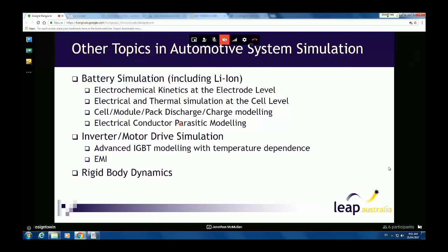So the amount of copper required to get electrical energy out from every single electrode to the two main connectors at the end of the battery is a very large web of various different conductors weaving through all the cells. So there's a not insignificant amount of resistance and capacitance and inductance associated with that web. And so you can choose to optimize that as an extra feature at the same time that you're working to optimize the chemical kinetics and the thermals of the battery.